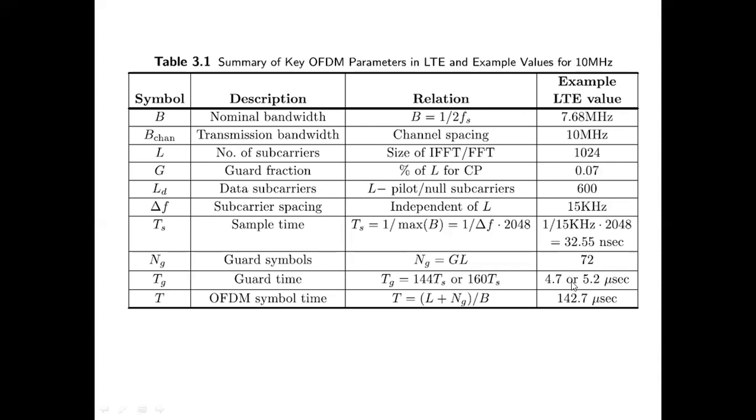That adds to certain loss, but it's a necessary evil, so you cannot avoid it. Whenever you send some data, there are lots of overheads. Out of 1024, only 600 are the actual data; the remaining are pilots, synchronization and all those things, as you saw in earlier channel cases.